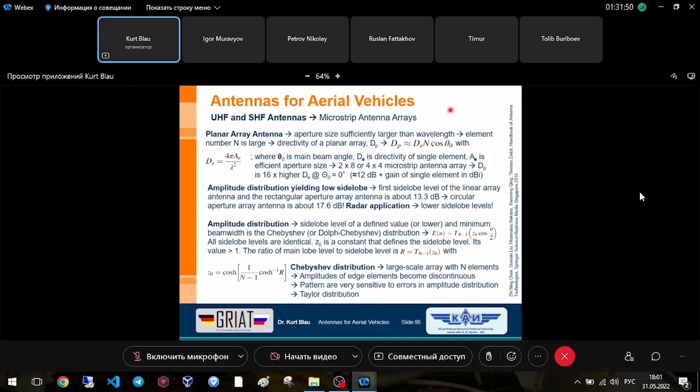Then we can use single element antennas in the form of a horn antenna. But here in this case, we have elements consisting of microstrip patches, but the patch itself has about, I showed you, with air as a substrate, up to 9 dBi as a single element.